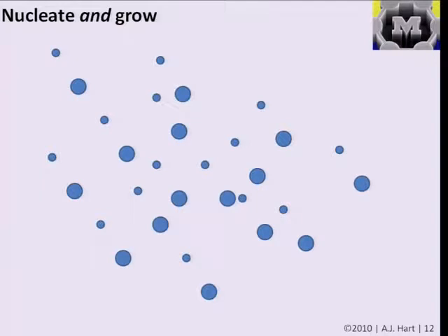But there's an important difference whether I can control my process. So I nucleate and then I grow, where maybe in the first step I only nucleate, and in the second step I grow some of the initial nuclei bigger, but I also form additional nuclei. And you can see here, now I have two distinct sizes, but really I'd have a broad size distribution, a case where if I am simultaneously creating new structures and making older nuclei bigger, I kind of lose control pretty quickly.